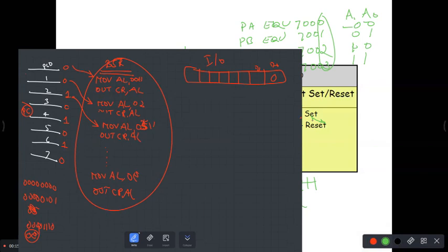Then what are the others? Port B. Which is that bit? Port B, D3. See, you are not using port B here, right? Are you using port B here? No, you are not going to use port B at all. In such cases, you make it 0. All other bits you make it 0. Except this bit. Why should this bit be 1? Because IO mode. Mode 0, I will take.